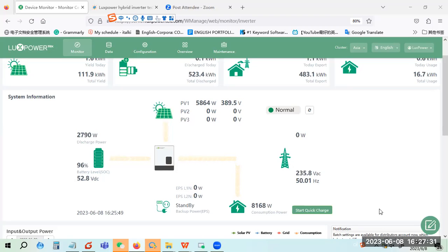So we just turn off the PV to make it discharge fast, and when it decreases to 90%, the battery will stop discharging and use AC to take the load. Yes, so the configuration for the inverter you get is already like a hybrid working mode, so you do not need to change any settings. Or we can update the data.